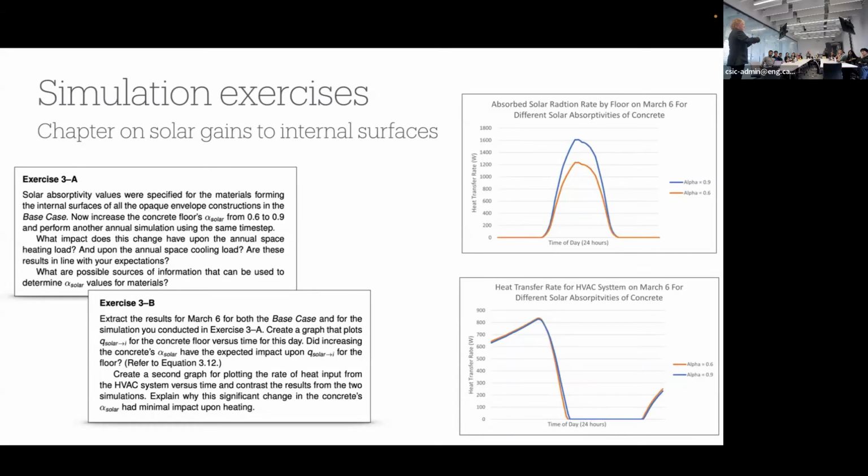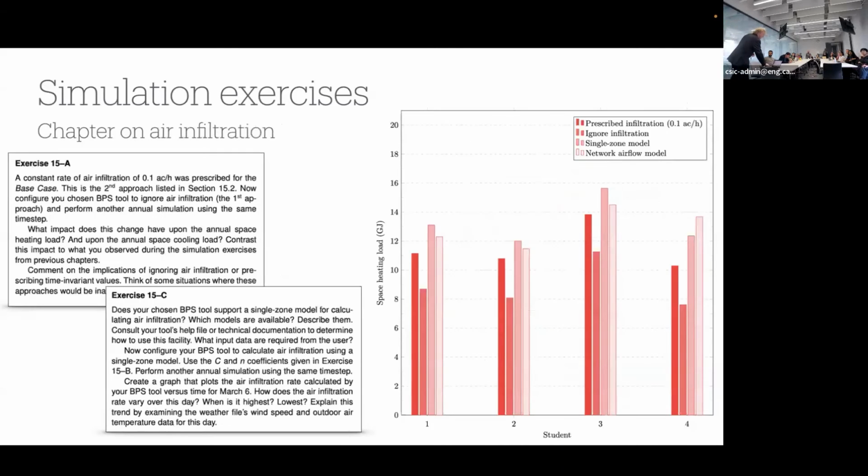It's inside the building envelope, and it's going to be redistributed to other surfaces through long-wave radiation exchange or convective heat transfer. So they develop an understanding that determining that quantity, solar absorptivity, is usually not that critical in the building simulation analysis. So that's information that they use to build up their experience.